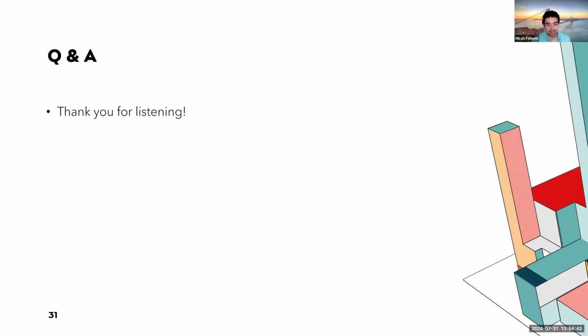And then on how to test. Again, it's a lot of general software engineering best practice. Do small changes and then test those changes in different ways. Test the edge cases. Give it inputs, geometries, and source configurations that will expose weaknesses in your logic. That's how you do any sort of testing: give it cases that are going to stress your implementation and look for holes. If you want to look for your source not giving you the profile that you expect, you want to set up tests to that effect.